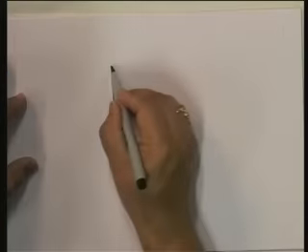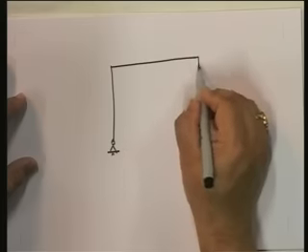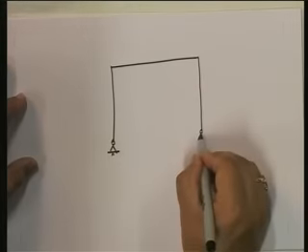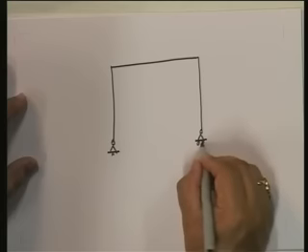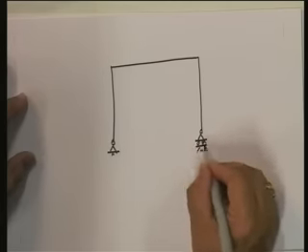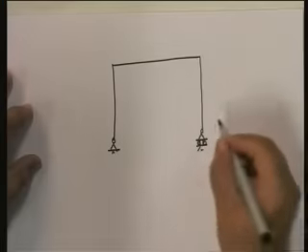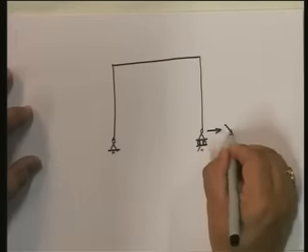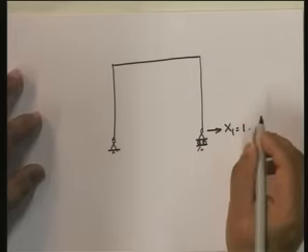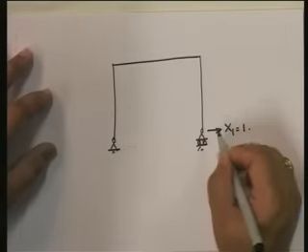Now remember that in the first method we are doing everything to the base statically determinate structure. So therefore there's nothing, I mean always I'm actually solving for this. Here was the next step, put x1 equal to 1 and find out what the thing will look like.